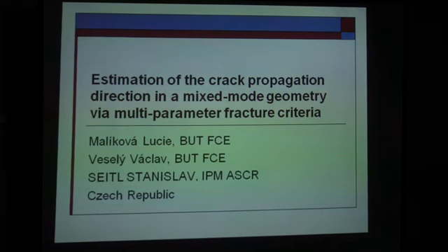We are now more focused on multi-parameter fracture mechanics, where we use more members to describe the stress field in front of the crack. And then, if we know the stress field, we would like to introduce these members inside the criteria for crack propagation.